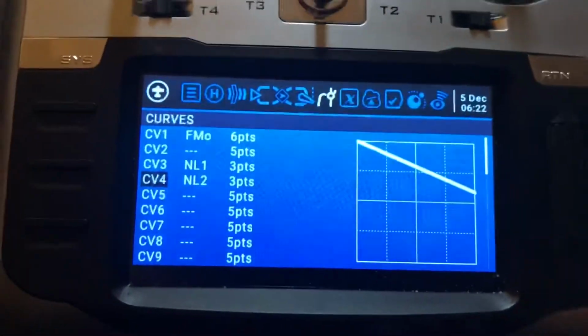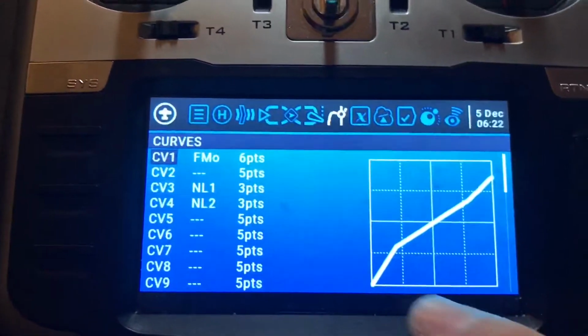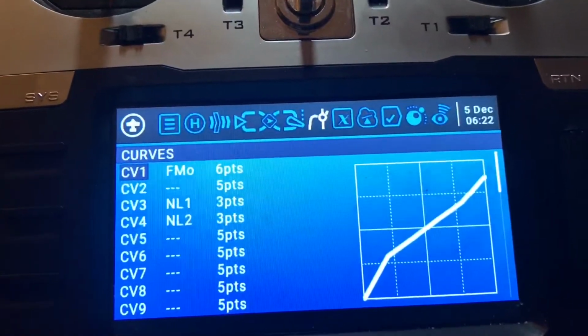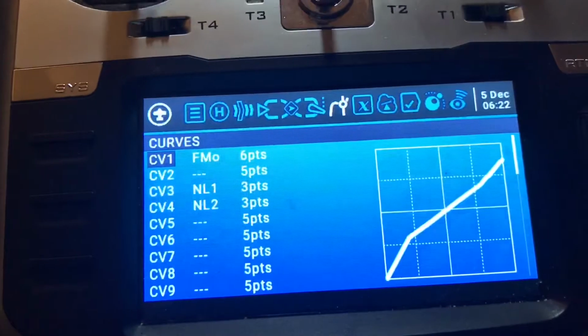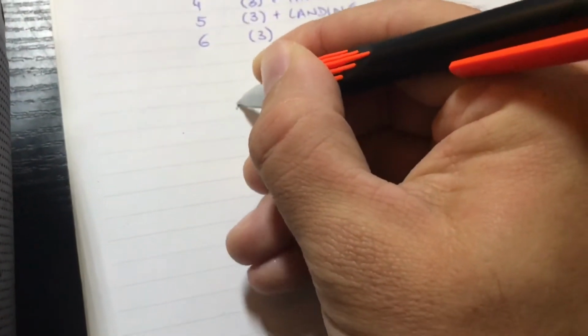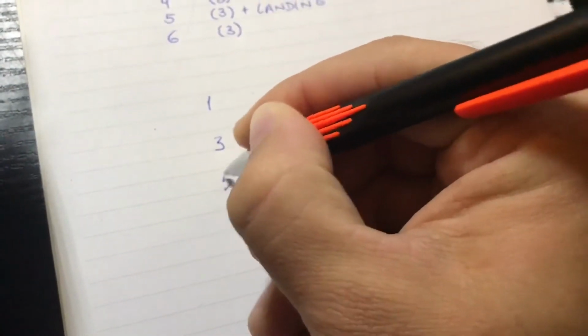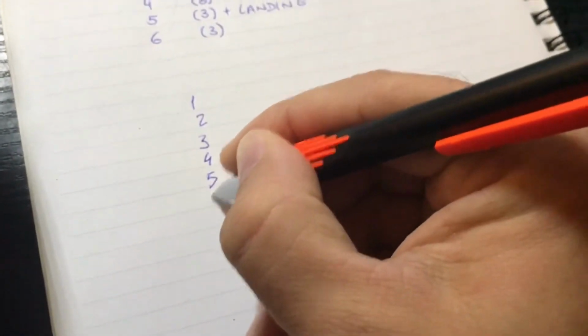on the Taranis, if you use just one curve like this on the setup that you often find on YouTube for Taranis, normally you end up having something like one switch position will be position 1, the next will be the 3, the next will be the 5, and then we go back to the 2, and then the 4, and then the 6.